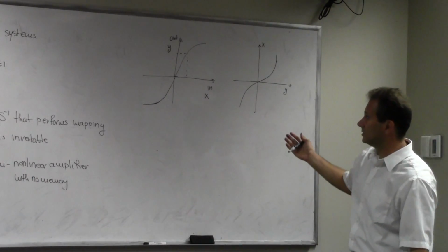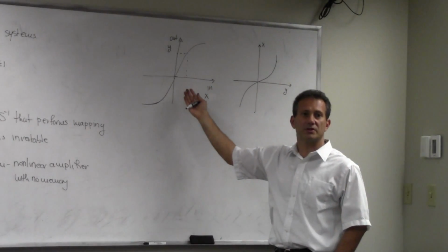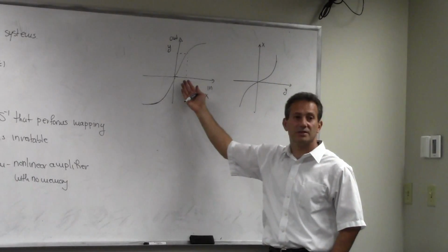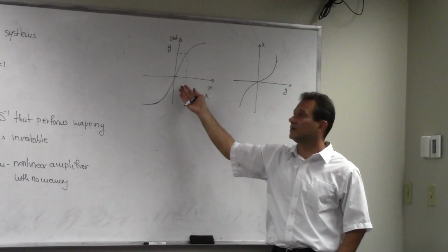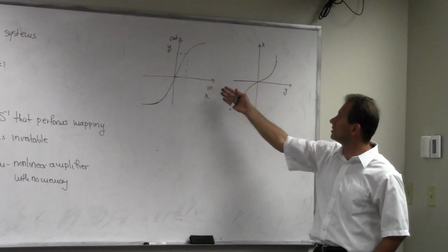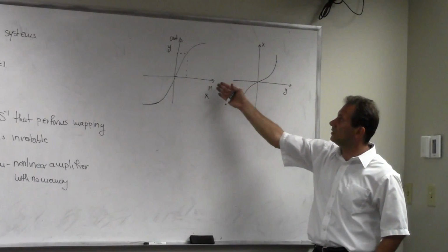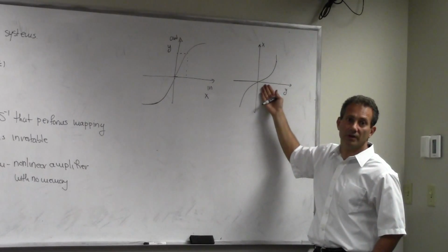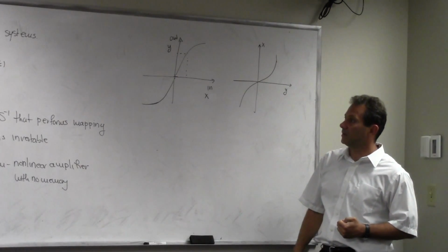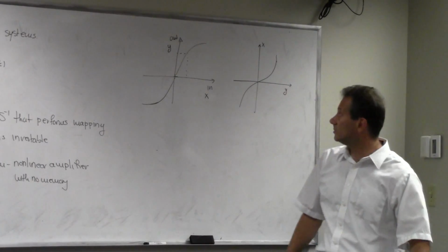We have this kind of system, for example, in voice processing, where we have A-law and mu-law compression. Those are examples of invertible systems. If I compress my signal on the transmission side using this kind of curve, then on the reception side I undo this compression by running my signal through the inverting function. Together, these two end up with a mapping that maps x of t into x of t. So that's an example of an invertible system.